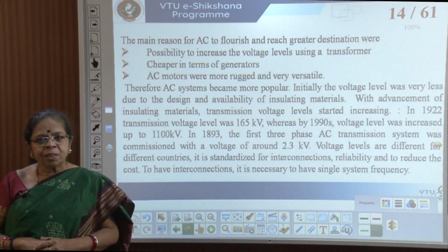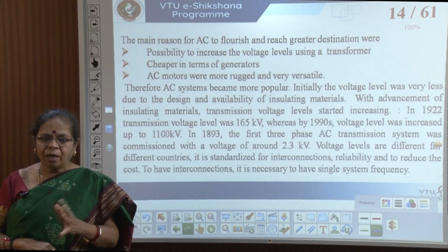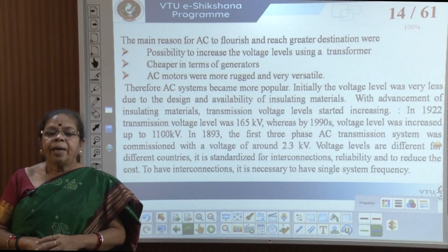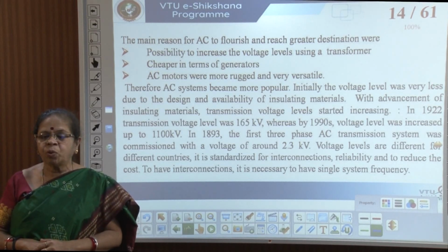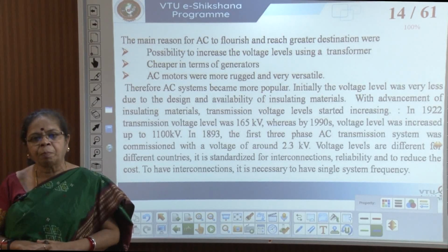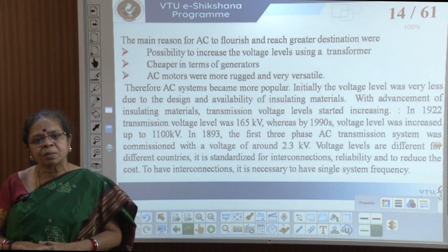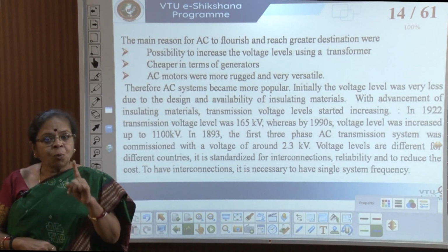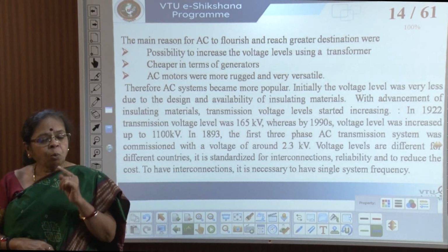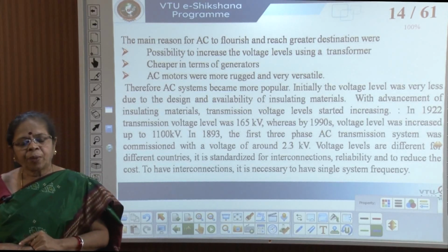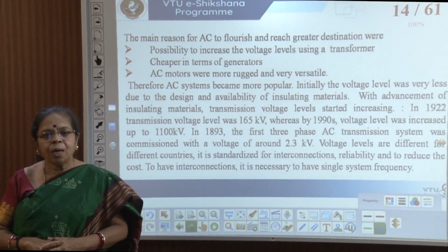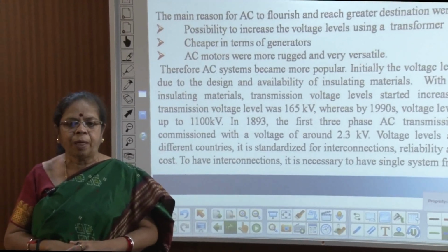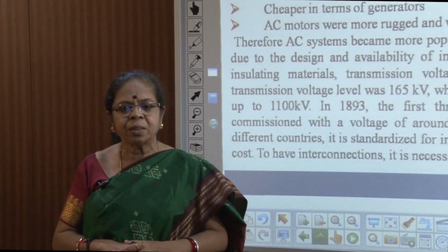Now, the voltage levels are different for different countries, and in a country it is standardized. So, in India, if you take our domestic supply, it is 230 volts single phase, and 230 volts is the RMS value. So, I want you all to keep in mind that in an AC system, whenever we talk of the voltage, we are talking of the RMS value.